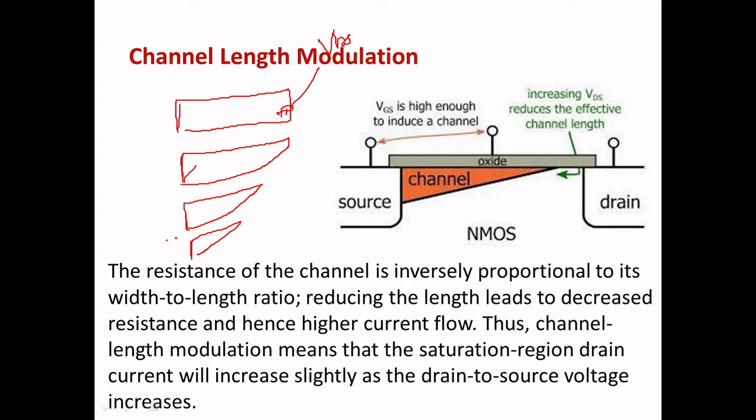See, you can see here at one point, this is your drain, and this is your source. So you can see the length is modulated. This whole part will be occupied by immobile charge carriers. This we used to say is the channel length modulation. Okay, I am not explaining in depth, just giving an intro to say what channel length modulation is. So the channel is modulated.